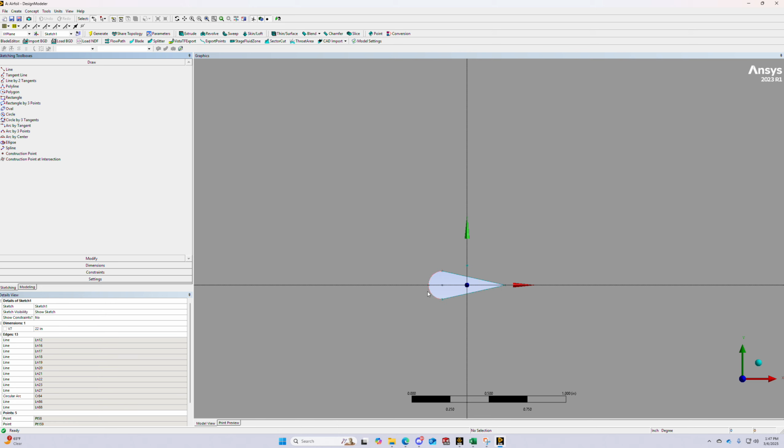So the length of the airfoil is supposed to be 0.5 inches, which is just given to you, and the radius of the circle is supposed to be 0.18 times this length here, the chord length, which would give you 0.09 inches. And so just to make this, you make that first line, which is the length, and then you make a second line here, and then you make a circle with the center at this part, and then you just drag it out to this point, which is going to be the radius of that circle.